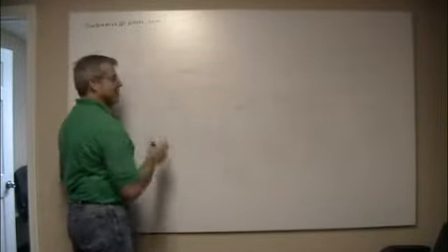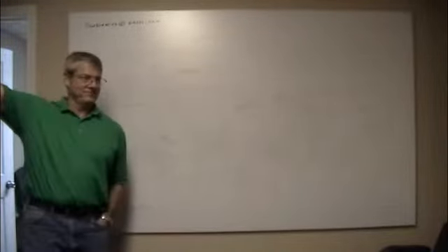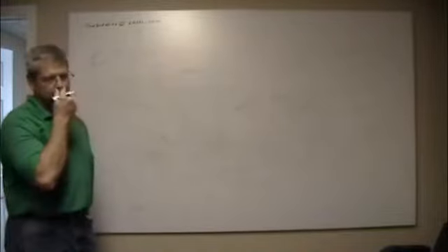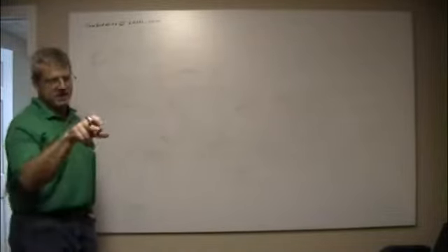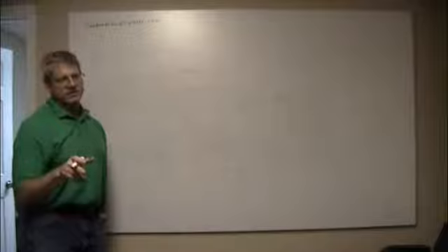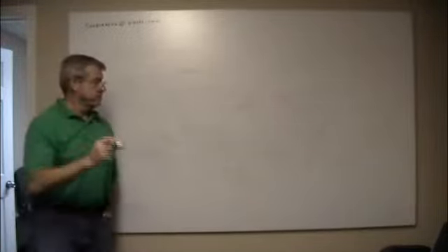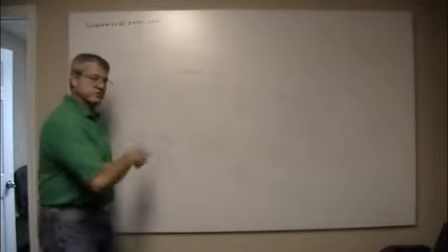Yeah. Well, and big relays are called contactors. Like for outside the building here to supply power, that'd be a contactor. With that big switch I have at work that goes ka-chunk when you... That's a contactor. And the reason they're big is you're pushing power through them. So we're going to get into this right now.